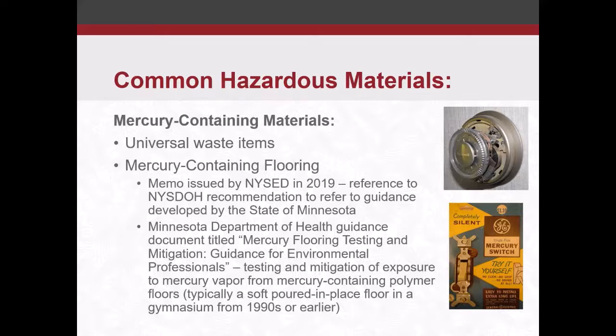And lo and behold, they were made with a mercury catalyst product. So a lot of times they're not much of a concern in place intact. Some of them might have high enough concentrations where they are off-gassing as is, but most of them, if they're left in place, are not a huge concern. But obviously when you do go to remove those, if you're not doing it in a contained, controlled environment, you could release mercury vapor, and that can be very hazardous and toxic to the occupants. So definitely want to control that when you remove it.